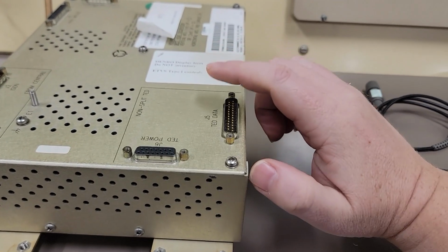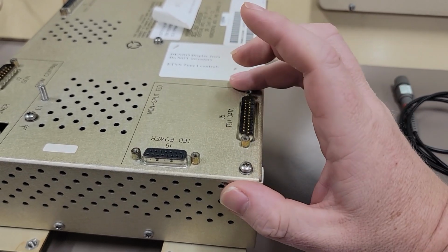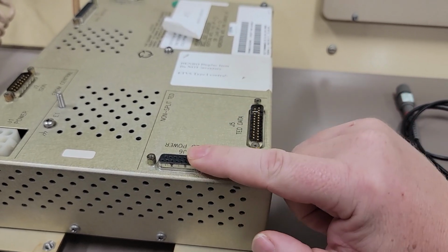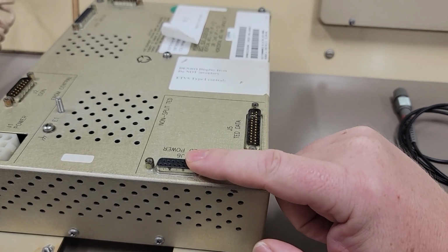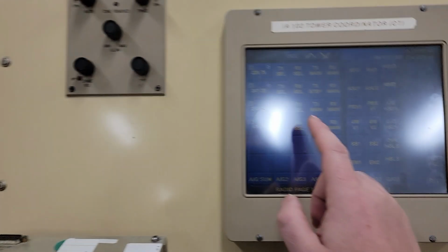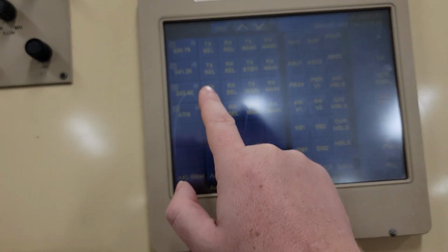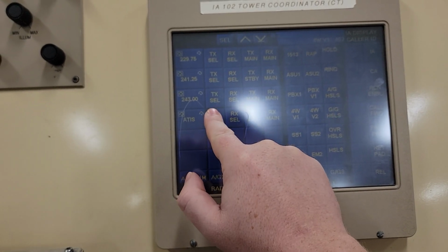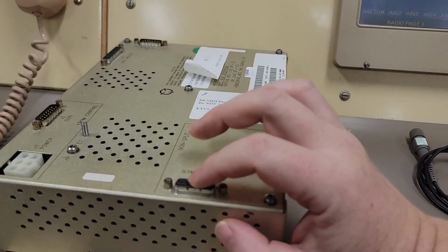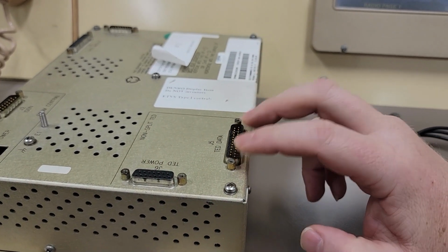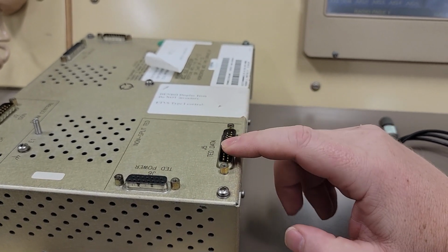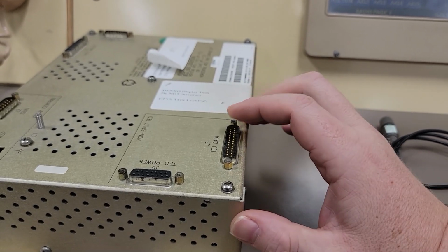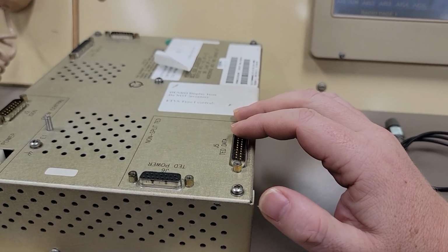Well, that means that at the output cables for my touch entry display, okay, now I've got two cables, TED data, TED power, and actually over the power there are two wires that carry our resistive membrane feedback from this for selection information. I'm not going to focus on this one for now. I'm going to focus on this. The TED data is what's going to carry my red, green, and blue, horizontal and vertical sync. Okay, but it does it in a very interesting way.